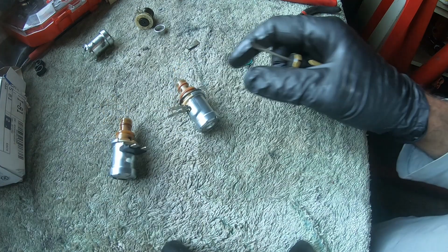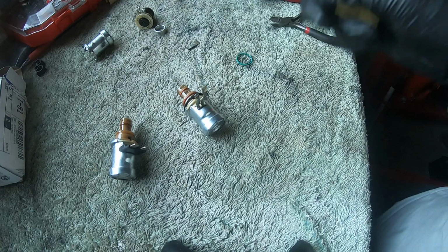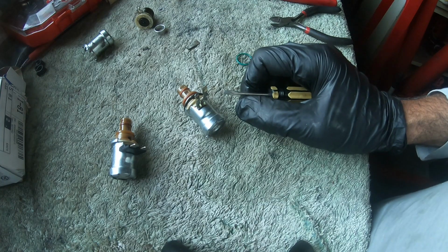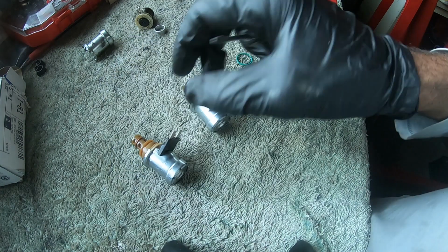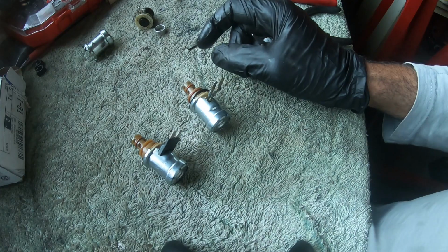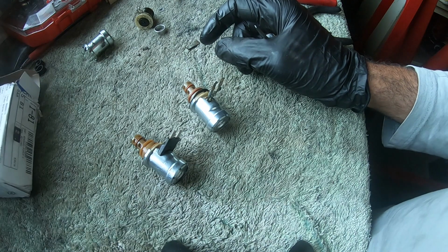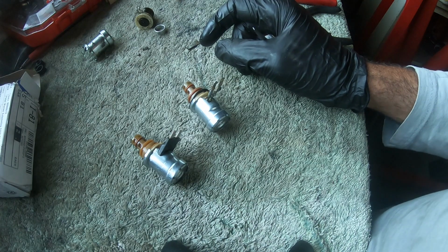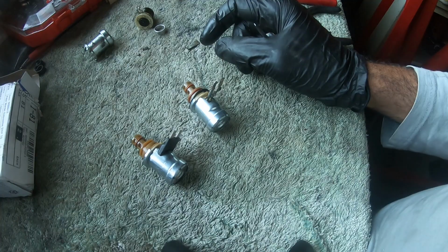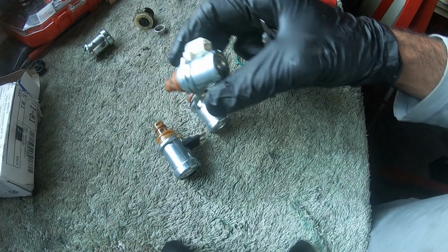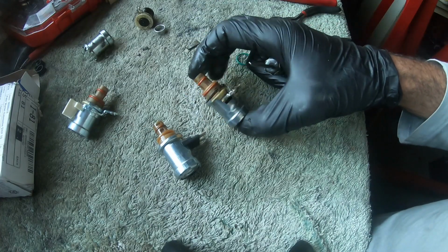So let's put it in there and see if it works, but so far I'm not really sure that the problem was this line pressure. I do know that the torque converter clutch solenoid VFS was bad. For that I have this replacement one, so I'm just going to put this one in as is, but this is the new one that I created.